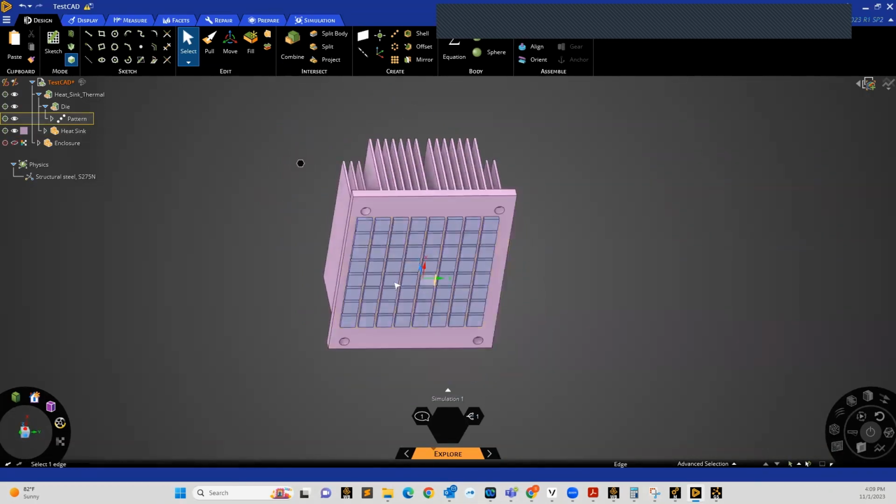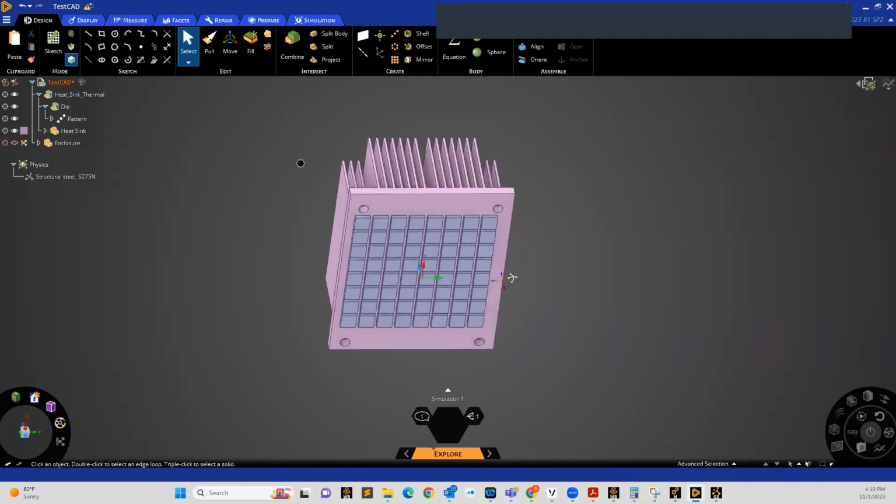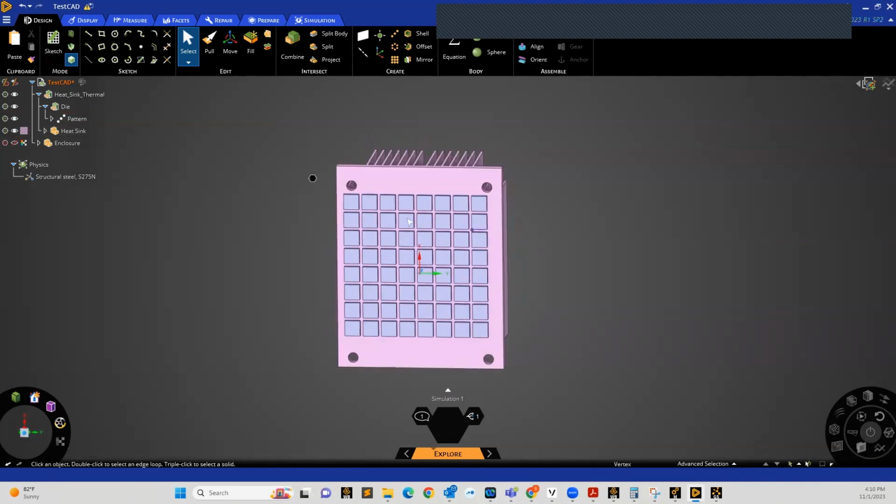And so what I've done is I've taken this die and I've shrunk it down a little bit, and I moved it up to this top left-hand corner, which is just kind of an arbitrary distance away from each of these. And then what I did is I used a pattern tool here in Discovery to create a pattern of these dies across the entire board. So now what I would be doing essentially, instead of applying the power to one large die here in the center, is I'm applying that same amount of power just spread out amongst all these little dies from within, mechanical here.